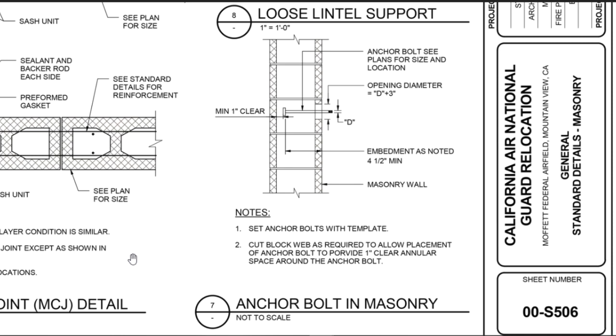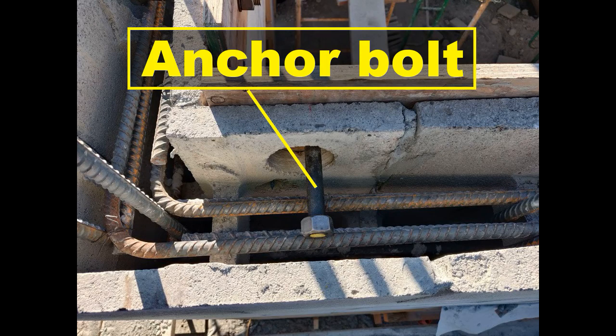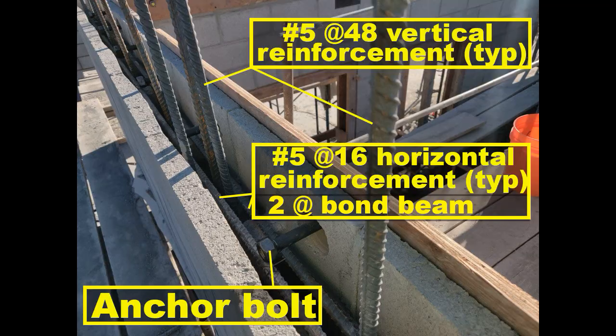Anchor shall be installed with 4.5 inches embedded into CMU wall with minimum 1 inch clearance to block wall. In the attached pictures, you can see anchor installed above bond beam and before grout placement. Final CMU rebar inspection is required before grouting.